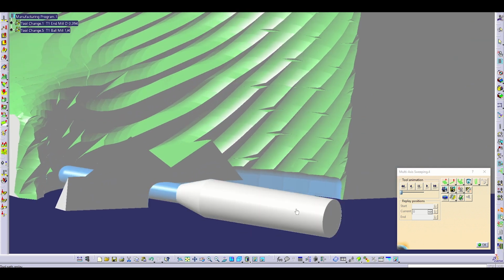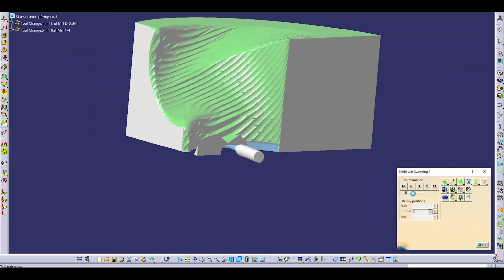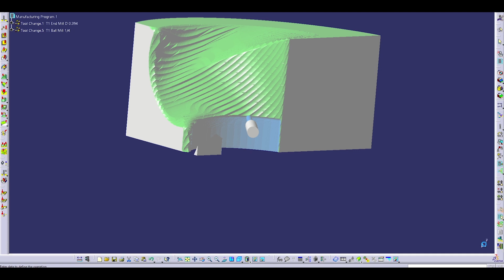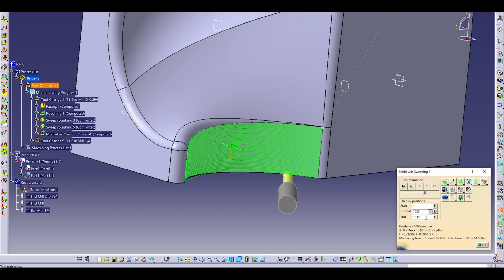And also a little piece on the bottom, that will be off. There's not going to be metal floating in the air when you're machining, so that's not something to worry about too much. But yeah, as you can see, the 5-axis is guiding it right along that curve, which you wouldn't be able to get that kind of accuracy with like 3+2 or 3. So that's what's good about 5-axis.